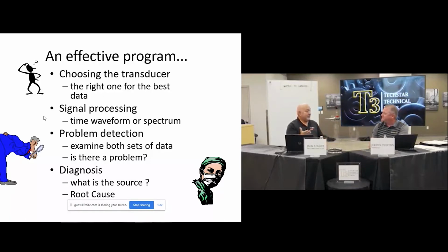Wow. So we did some testing on it, and we found out that it had electric current going through it, and we were able to diagnose that, hey, they just had an outage and they didn't attach the ground wire back to it. That'll do it. So you're getting arcing basically, and it was causing a defect in the outer race.